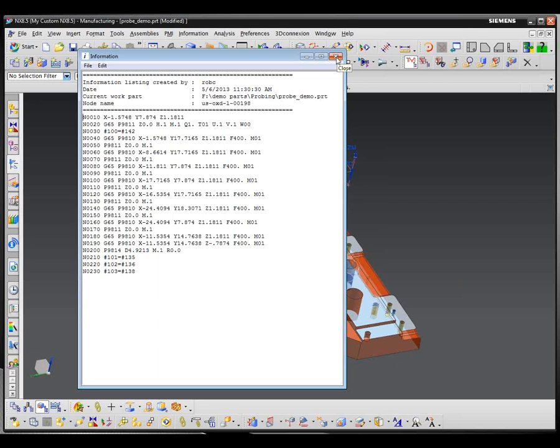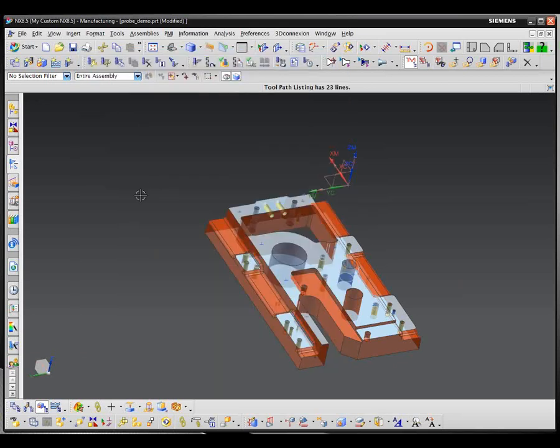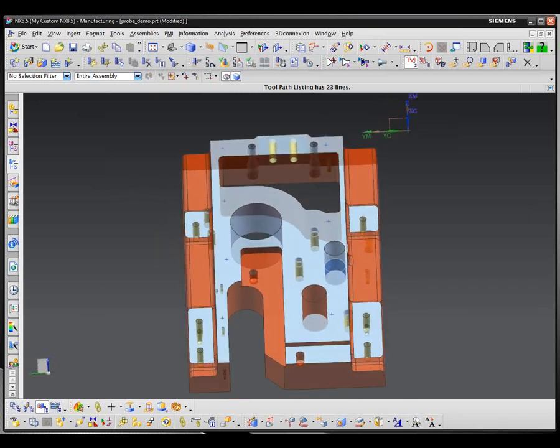The advantages of having on-machine probing is, rather than having your operator try to set up each individual job, as long as your fixturing is good enough where the probe can get into the different features, the machine itself can pick up its own coordinate systems and update its fixture offsets and start to program. Where I used to work, we did this all the time. It's a huge time saving, and it eliminates a lot of human errors, reading indicators, and mitigates some of the differences in skill levels between operators. So that's pretty much the conclusion of my demo, and we will continue on with our presentation.